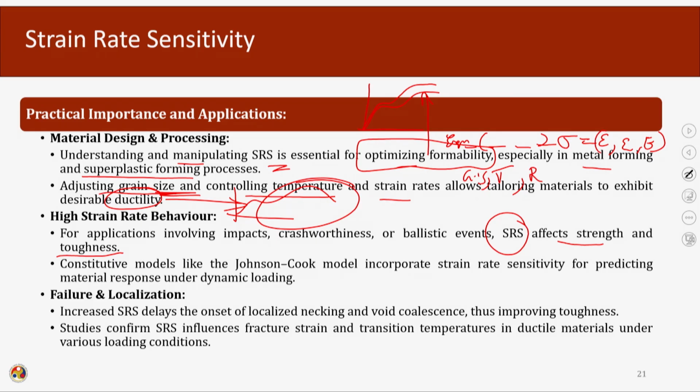One of the widely used constitutive models is the Johnson-Cook model. Using this constitutive model, we can use the material model in our finite element simulation, or in our analytical calculations, for predicting the material response, the behavior of the structure by which this material is made, and the effect it will have as an energy absorption material or as a sacrificial cladding to act against dynamic events like a crash event, impact event, or blast event.